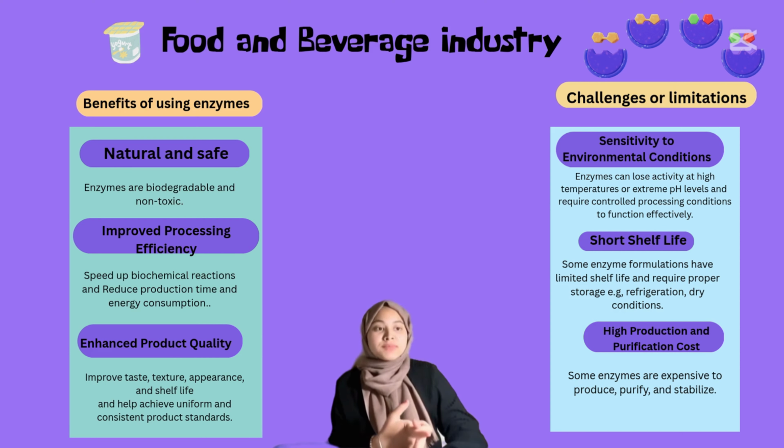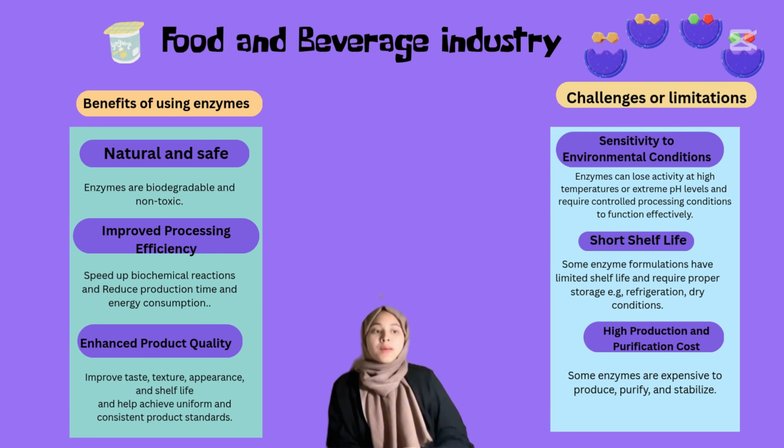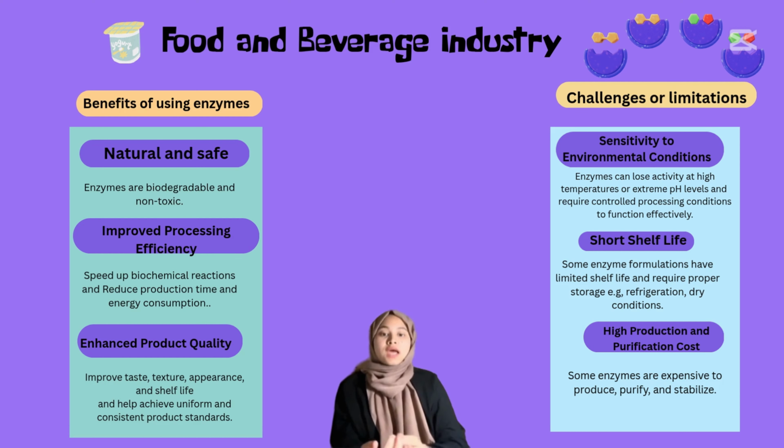Next, challenges or limitations of enzymes. The first one is sensitivity to environmental conditions. As you know, enzymes can lose activity at high temperature or extreme pH levels that can denature them, and they require controlled processing conditions to function effectively. Next, short shelf life. Some enzyme formulations have limited shelf life and require proper storage, for example refrigeration and dry conditions. Example, lipase. Why short shelf life? Because it loses activity quickly if not stored under ideal conditions, for example cool, dry, and stable pH.